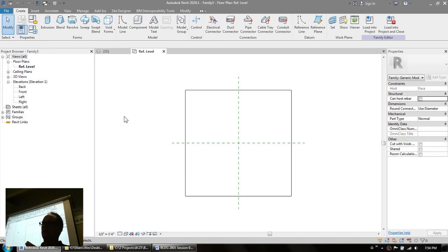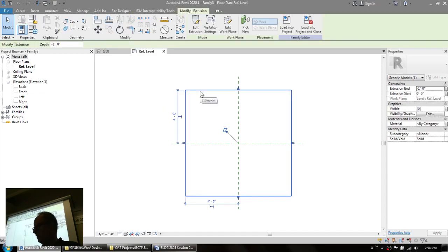So just so you have a sense of how this is all oriented, we are looking downwards in this view. This is not a wall elevation. You're presented with, Revit just calls it an extrusion, so you're looking downwards. So we're building this window as if it's lying on the floor. In the window template, we build the window as if it's standing up.